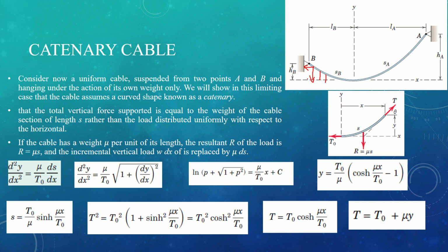Now, if you look at the free body diagram of this finite portion right here, this very small portion of cable length, let's say S, measured from the origin, which, if you remember, last time we talked about, the origin is the lowest point of the cable, and this will be considered as where dy by dx is 0, where y is equal to 0 and x is equal to 0. So we have developed the boundary conditions. The origin is shown, right?